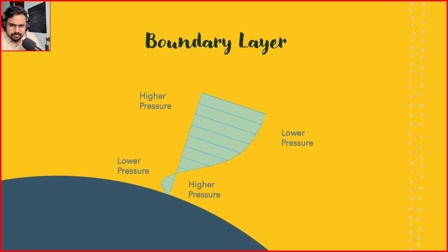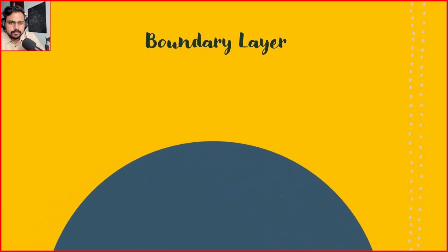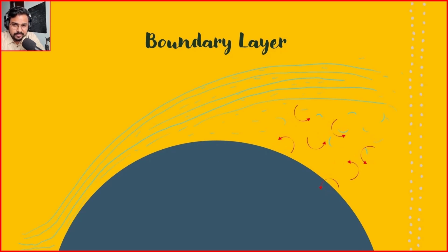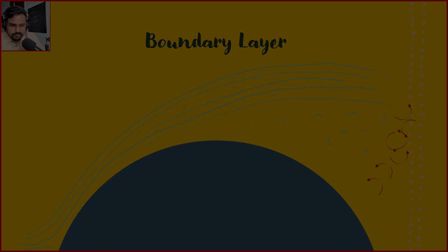This is precisely why Bernoulli's principle coming into play, as well as the boundary layer separation coming into play, both constitute why your flow separation is actually happening. Now, let's take an interesting approach towards understanding what this physical phenomenon looks like numerically using OpenFOAM. So I'll talk about the tutorial problem that we have with vortex shedding. I'll discuss essentially the physics of it, explain what the results exactly mean and what we can infer from it.